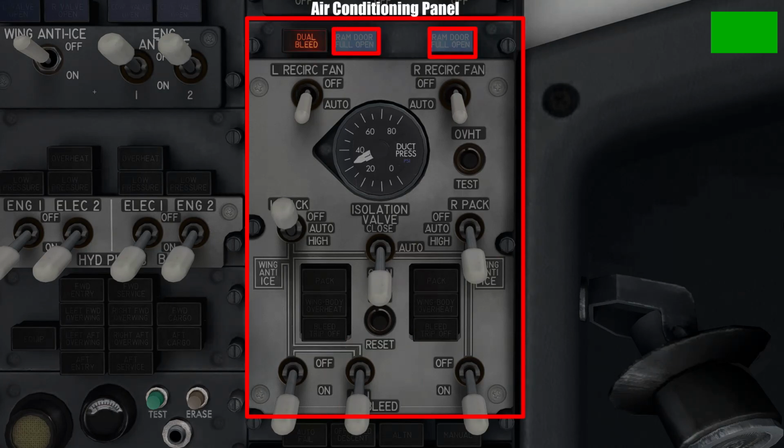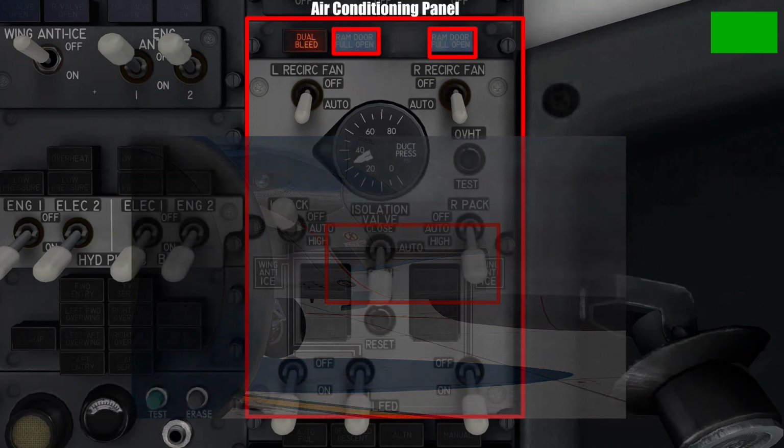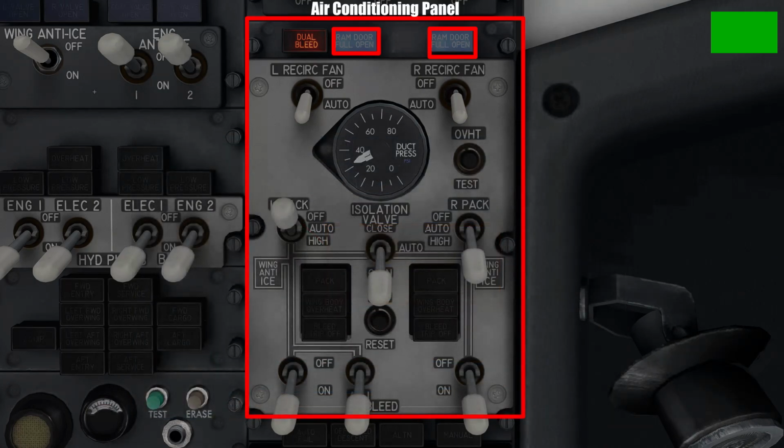As for the ram door full open lights, they come on only on the ground. This is because the ram door is a small physical valve on the outside of the aircraft that lets cool air into the pack system to allow it to cool the bleed air produced by the engines. During flight, having the ram door open partially will suffice, as the cool outside air is entering the ram door at a high speed. On the ground, however, when the aircraft is stationary, the entire ram door needs to be opened to use the cool outside air for the packs.